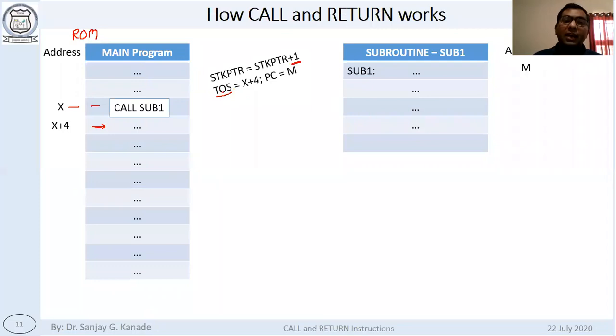Okay, at that TOS we write the address X plus 4. What is this address X plus 4? This is the address of the next instruction to the call. Okay, the address of the instruction which is next to the call in the main program, in the calling program. So this X plus 4 goes to stack, and now PC means what? Program counter is loaded with value M.